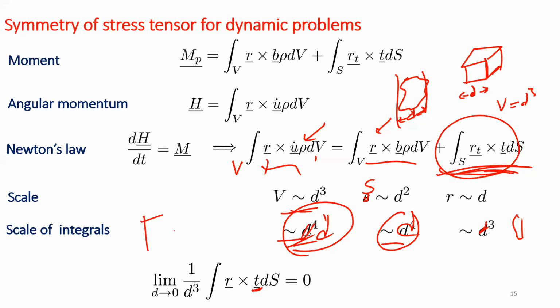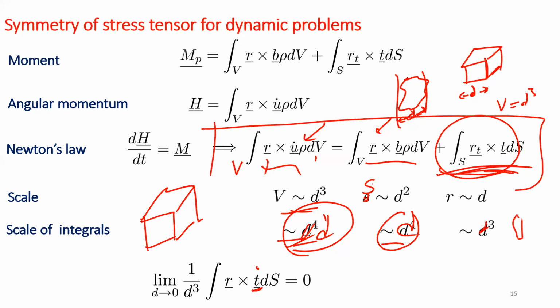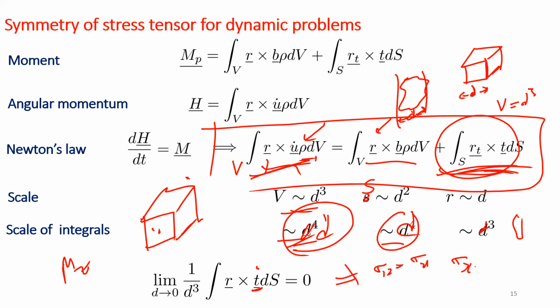So we pick up a cubic element because whenever we define stress in Cartesian, we are working on a cubical element. And you expand traction in terms of stresses. So now if you have observed, the time component has vanished. By doing such an analysis, the time component has vanished, and if you take any two opposite faces and try to evaluate, say, the moment about z, then you will again get the same set of results, saying sigma 12 is sigma 21, or sigma xz is same as sigma zx.